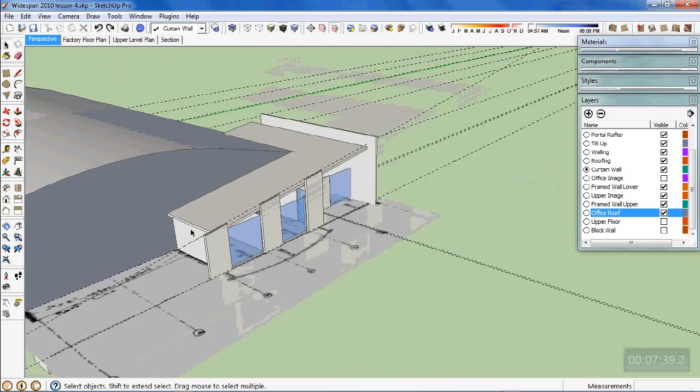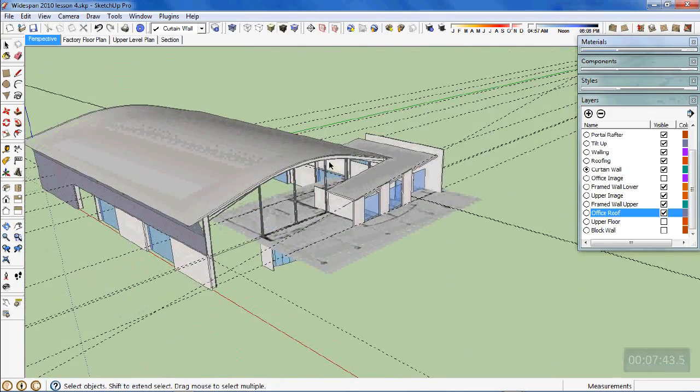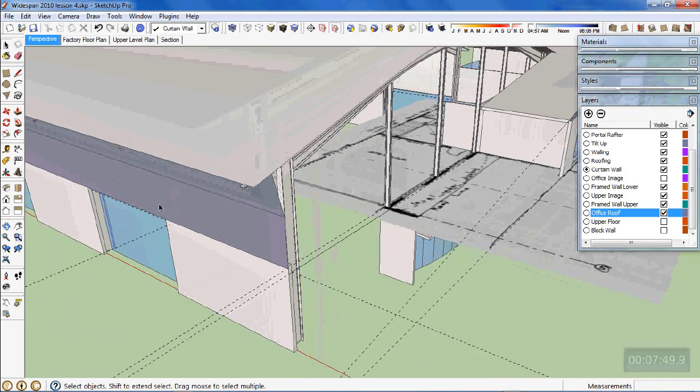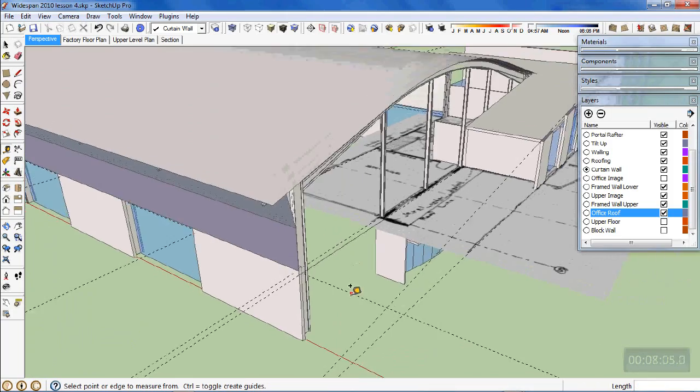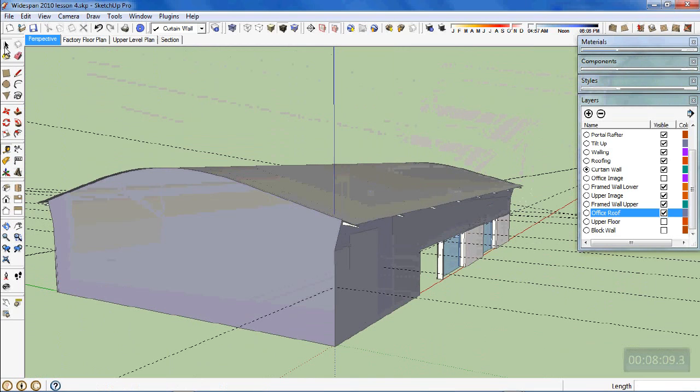So to get that front wall there, probably the easiest way is keep the 280mm offset line. So if you've got rid of it already, come back to this one running through the portal frames, the grid line, and give yourself a 280mm offset line. And remember, that's the front wall of the wall cladding that sits on the factory frame. So you've already done that up the back here. So simply take a copy of the whole of that face. So click that face and copy it.